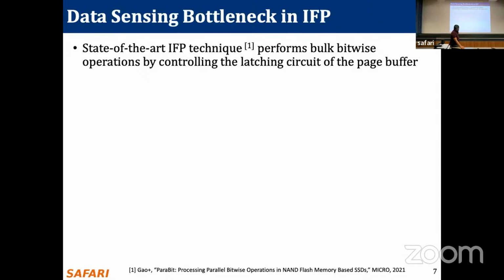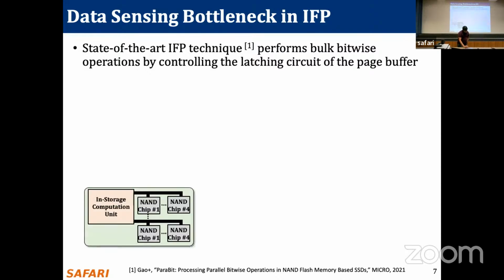In the state-of-the-art IFP technique, which is ParaBit, they perform the bulk bitwise operations by controlling the latching circuits in the page buffer. So here we have a storage device where we have an in-storage computation unit and a number of flash chips connected to each channel.